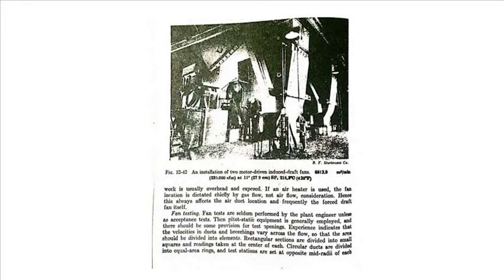Experience indicates the velocity in ducts and breechings varies across the flow, so the area should be divided into elements. Rectangular sections are divided into small squares and readings taken at the center of each. Circular ducts are divided into equal area rings, and test stations are set opposite the mid-radii of each.